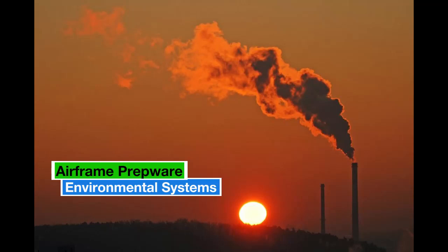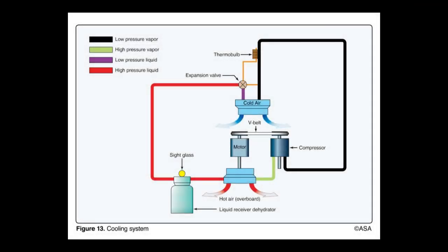When an aircraft's oxygen system has developed a leak, the lines and fittings should be bubble tested with a special soap solution manufactured specifically for this purpose. Refer to Figure 13.